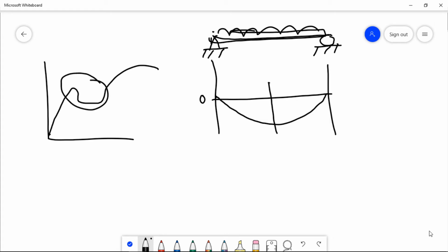When the yield point comes at the center section of the steel beam, the beam loses its moment capacity. Beam is going to fail, which means the beam will no more take the moment. So at the center the beam loses its moment capacity.